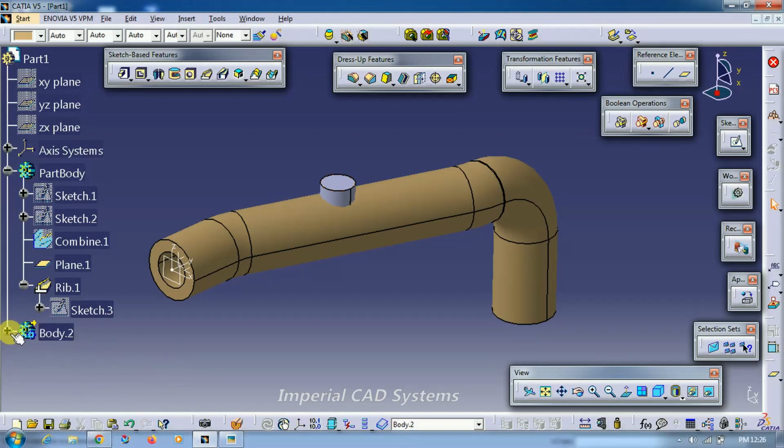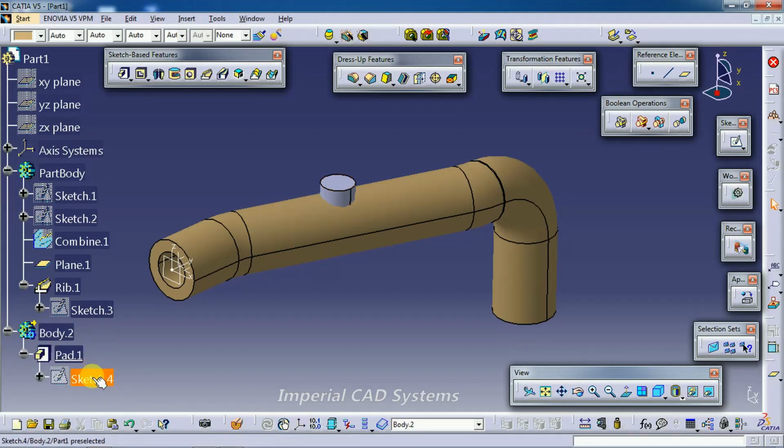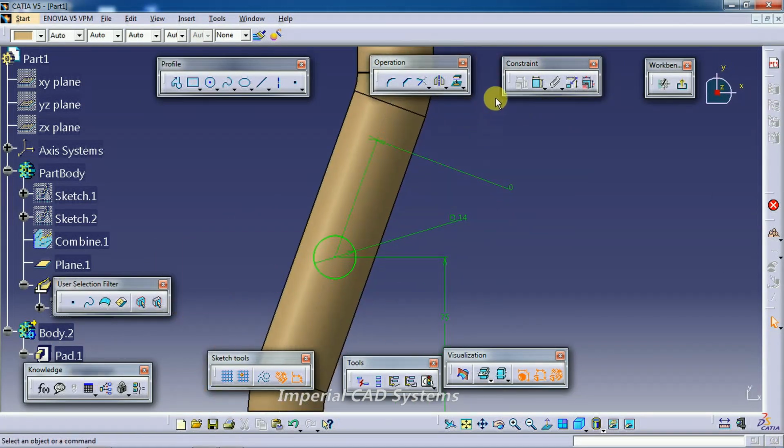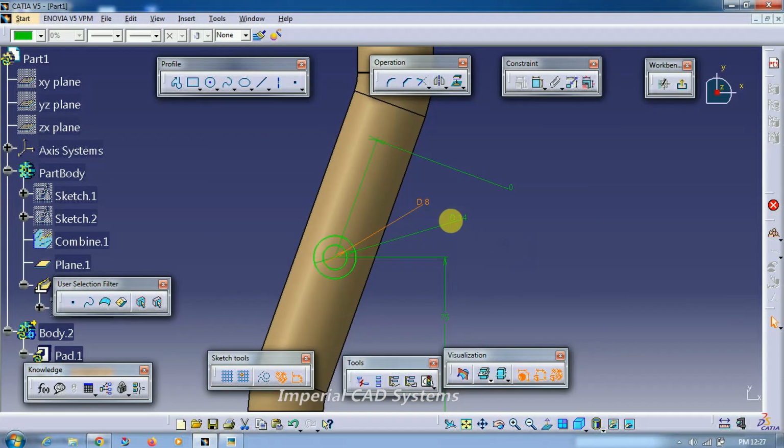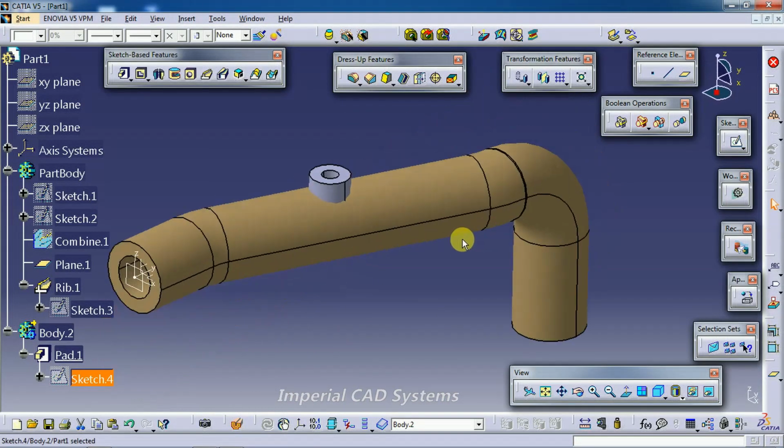As it has a hole inside, in the sketch itself we take 2 circles. I take 8 mm, and a still smaller hole, 6 mm, exit, that's it. As we are in body concept, I apply a color and go to union trim.